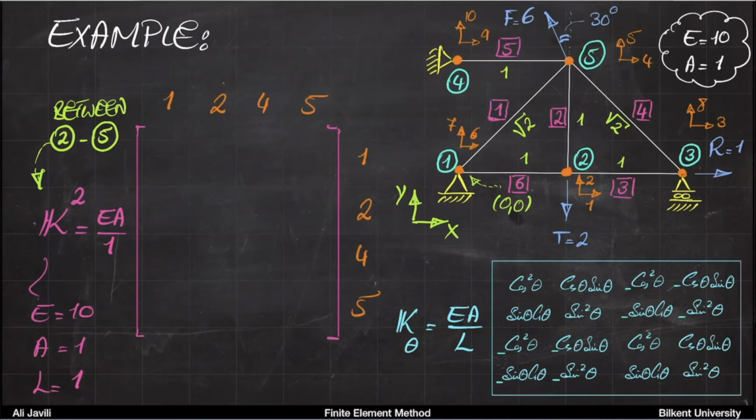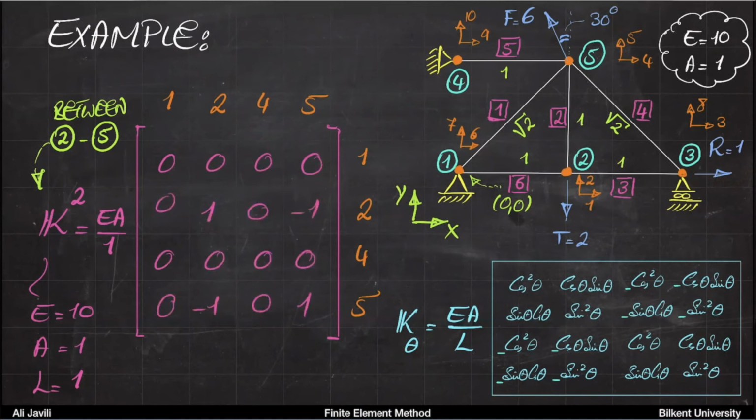And then inside the stiffness matrix itself, you just construct the components according to this. What is the angle of element 2? It's 90 degrees. So that's a good angle because most of these things will be 0. You get zeros completely here. You get 1, -1, -1, and 1, 0, 0, 0. Right? So that's that. That's element 2.